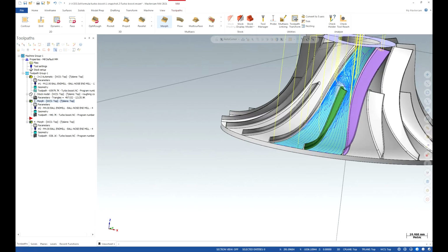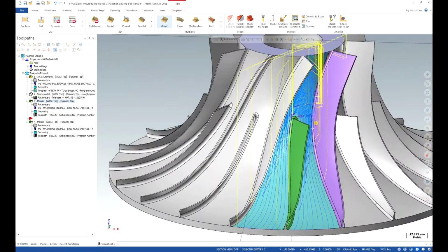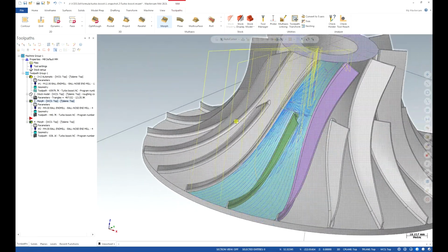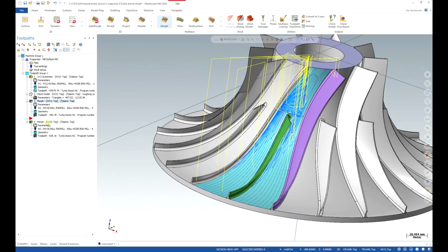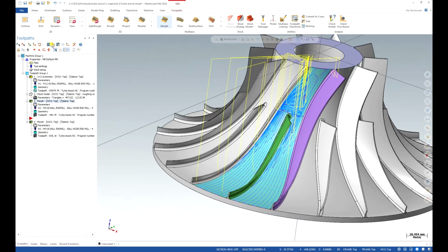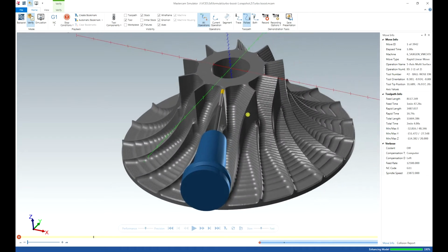and let's see our toolpath. Okay, oh good. In this way we have one section of the floor roughed out complete. At the end of the programming we will translate this toolpath around the part. Let's see on the verify how our toolpath looks like.